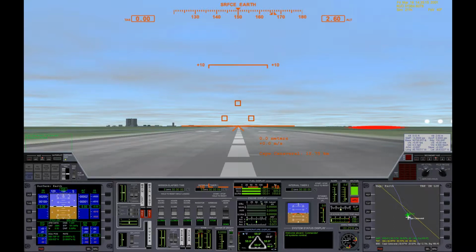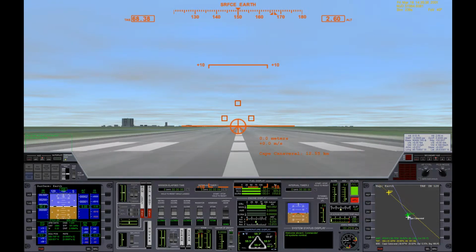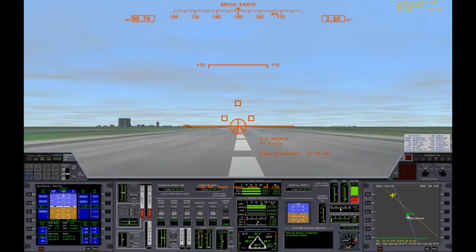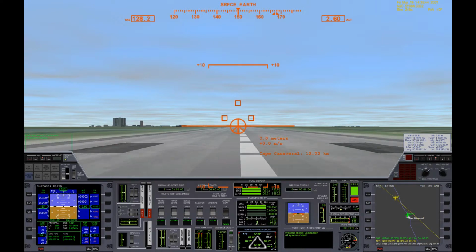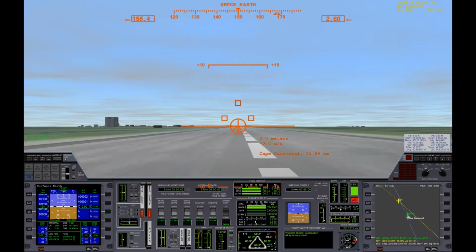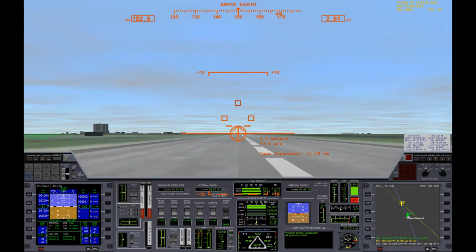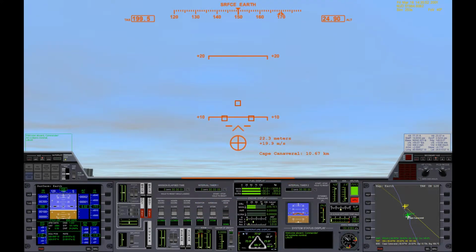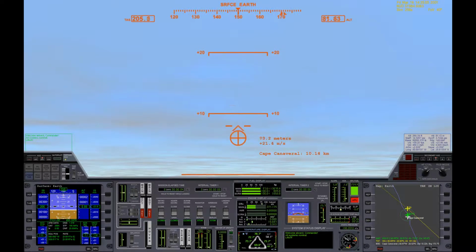We're going to take off by applying full power, and I'm going to move pretty quick because things all together go very quickly. That's what I'm trying to say. 3, 2, 1, now. 100 knots. Takeoff commit. V1. Rotate. Okay, I'm going to rotate up now to 10 degrees up. We're airborne, throttling back to 40% to prevent excess aerodynamic pressure.